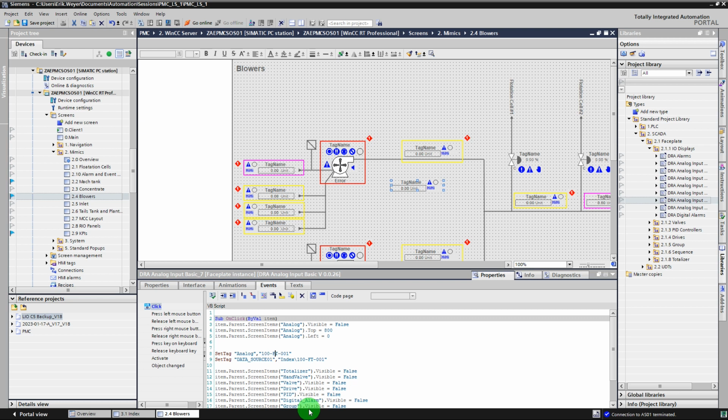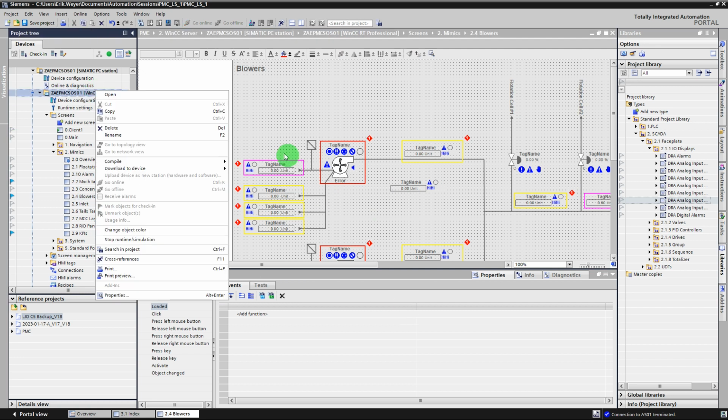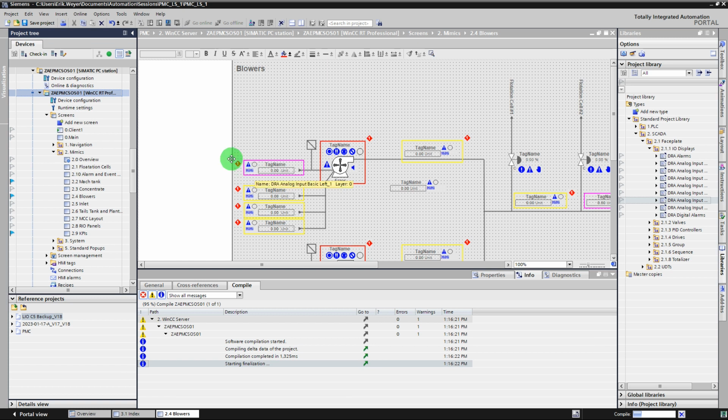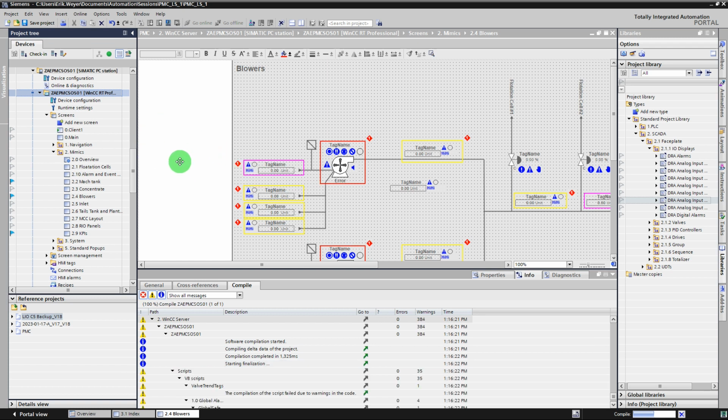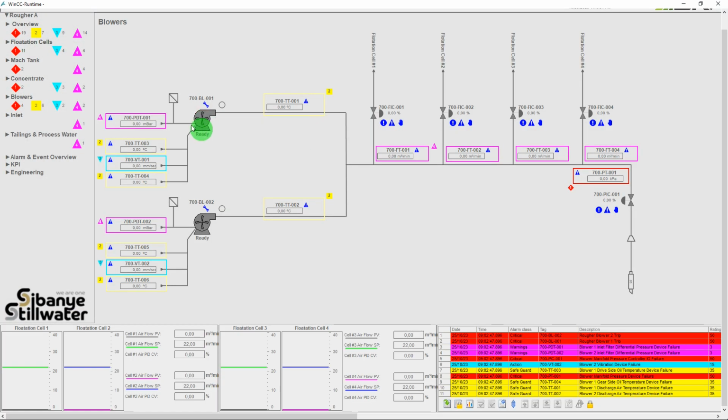So simple one, I just need to adjust my tag to 100 TT001, and for future I'm going to actually do my trend as well, although the trend will only be covered in part 3. And this is basically it to establish the faceplate. So I can just give the SCADA a compile, save my project, then I will open it back up and just refresh my page.